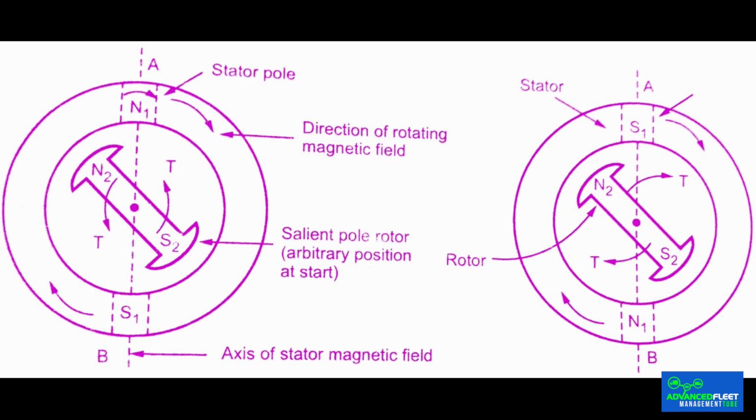The controller sends voltage to the stator coils, thus creating a magnetic field in each of them. The closer these coils are to each other, the better the performance. The rotor has its own magnetic field. Since opposite poles attract and like poles repel, the rotor aligns with the stator field. The voltage transmitted by the controller to the stator is alternating in nature, resulting in the rotation of the magnetic fields within it. Since the rotor aligns with the stator field, which is rotating, the rotor will rotate with it.